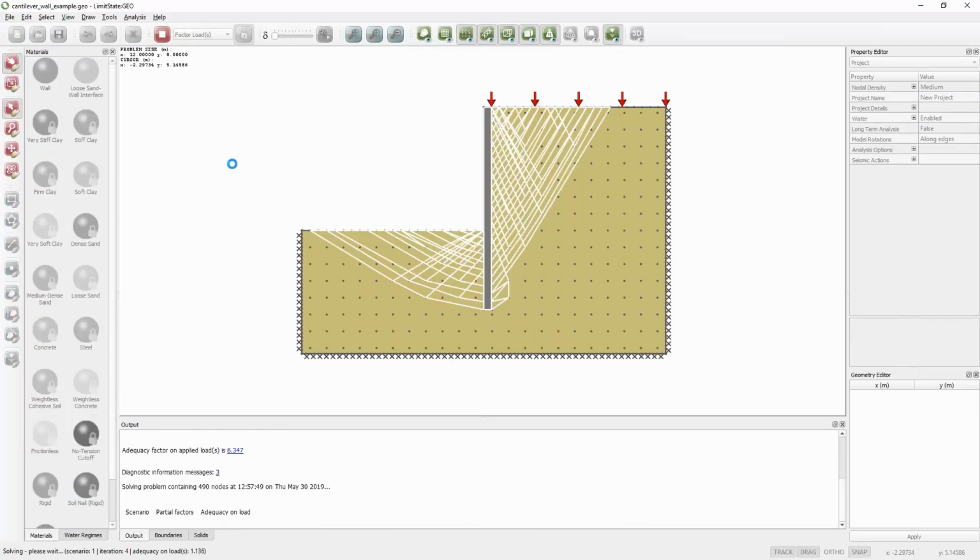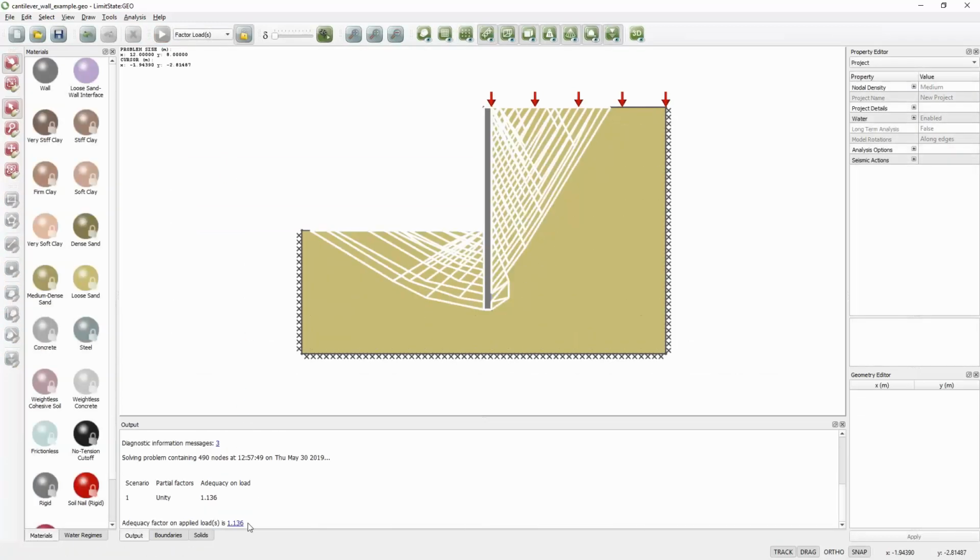If I analyse that problem, then I get a factor slightly bigger than 1 actually, but we're getting closer to that, so a little bit shorter, and then we'd have a length that was just on the point of collapse. And if we'd been already applying, for example, Eurocode partial factors, then that's what we'd be looking for.